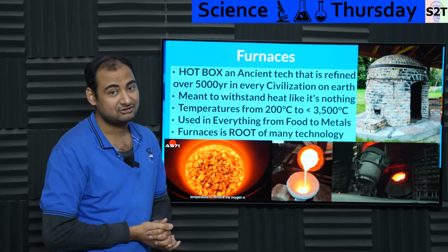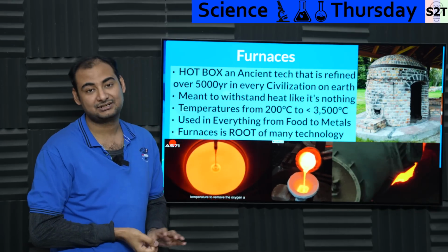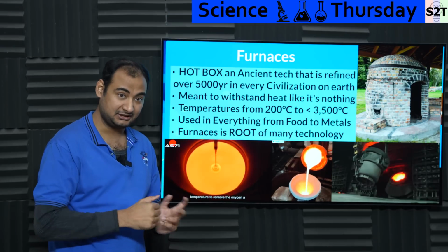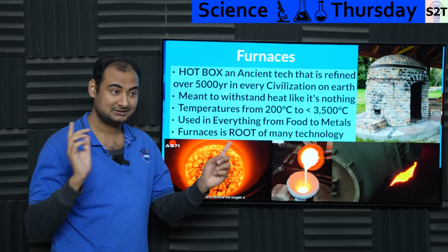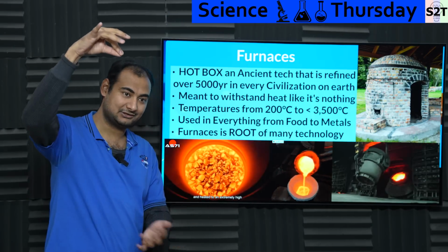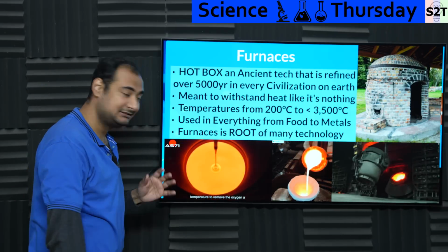For example, you cannot have oxygen there. Most likely you would require either to pull vacuum or argon purge it. So that has to be done. And not to mention, you have to spin a molten material, which is at very high temperature, and then you have to slowly pull something out of it. Yeah. So let that be very clear.